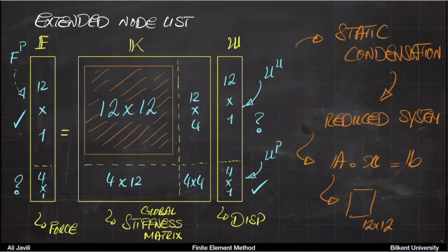And then, as I mentioned, again, back to the question that one of you had, there would be this static condensation process basically, and then you come to this reduced system. So you would call this the reduced stiffness matrix. This is the reduced stiffness matrix.